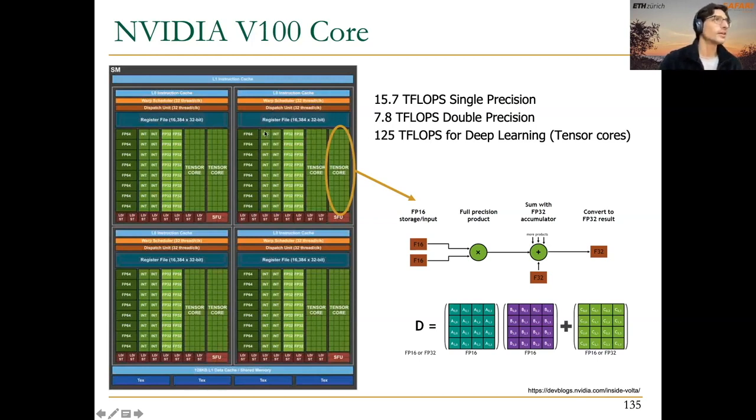What I would like you to check now is that we have here different compute units or different execution units or functional units. Observe how we have units that are specialized for FP64, so double precision, here integers, here floating point 32, here we have load and store units, and here we also have these special function units that execute transcendental operations, right? Like for example, sine, cosine, etc.